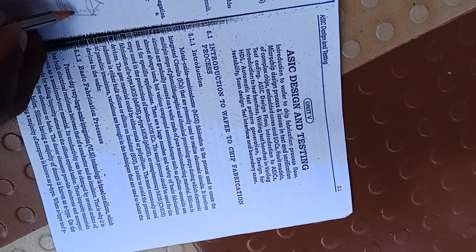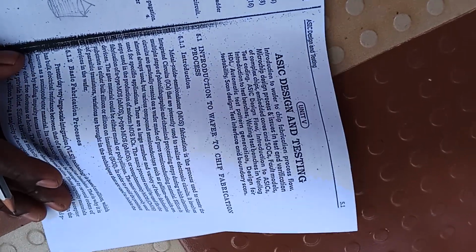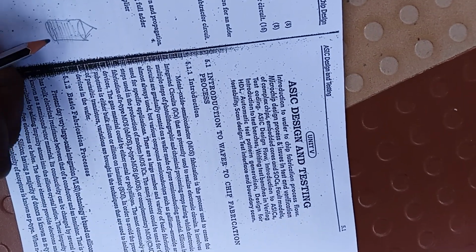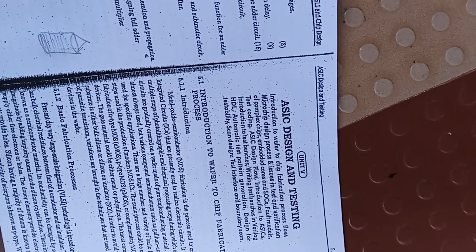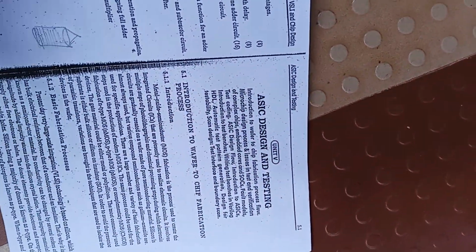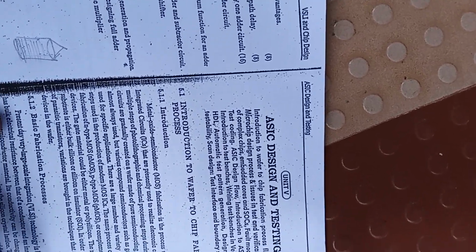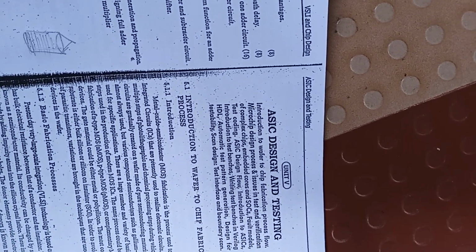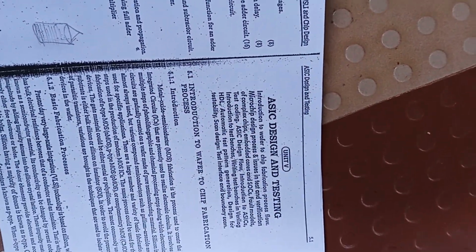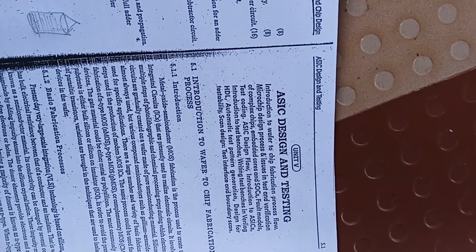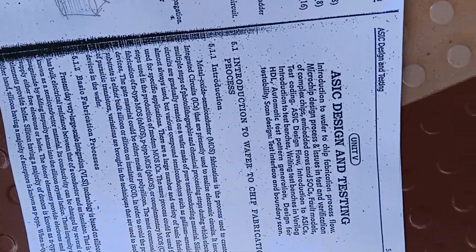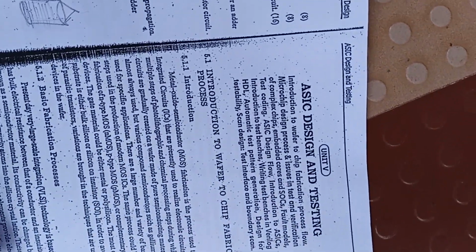After that it has to be sliced. So this is the wafer. This is the first step, wafer preparation. In the wafer preparation, these are the steps. Pure sand has to be melted into a solidified rod, the ingot, and this ingot has to be sliced with high accuracy machines, with very minute thickness. Because the size will be in nanometers, micrometers and all, it has to be selected accordingly. So this is the wafer preparation step.